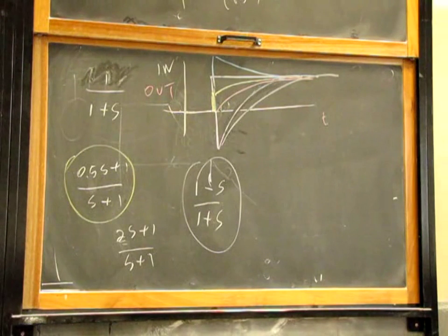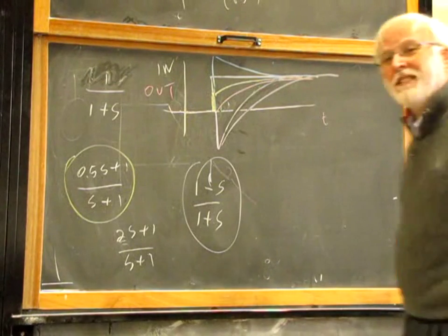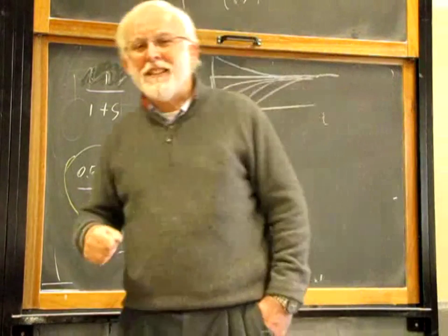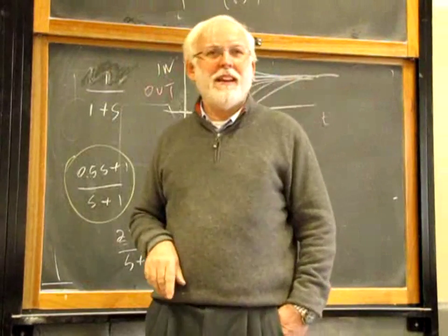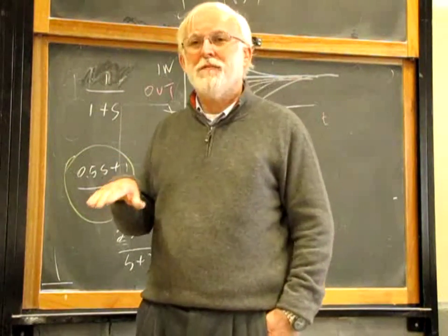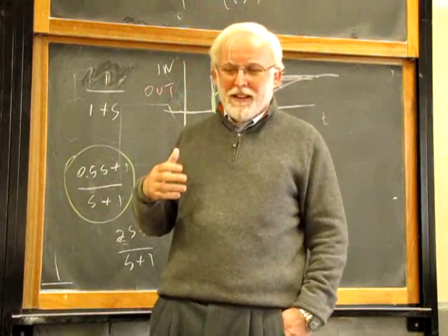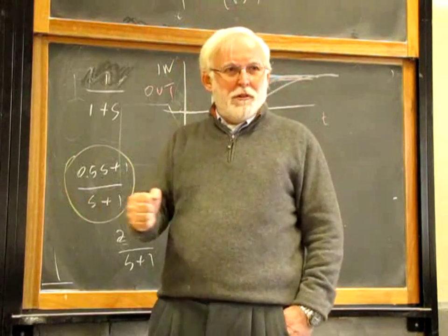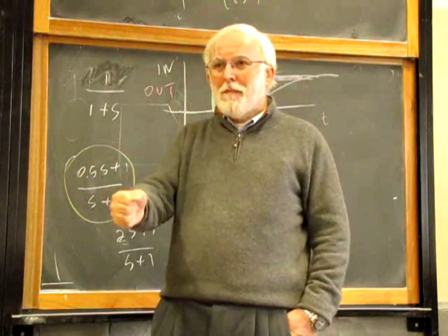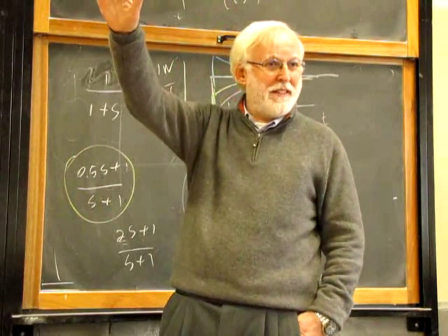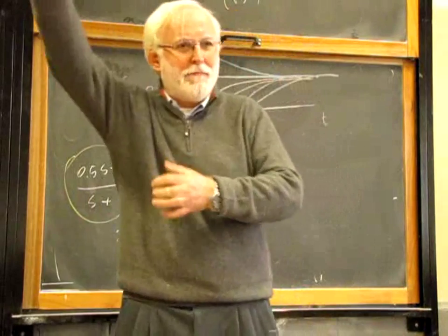Supersonic fighters: when you pull the yoke, it's not a yoke, it's a stick in a fighter. You pull the stick to go up, the fighter goes down and then climbs. And this effect, the right half plane zero, was found by an engineer who solved the system and said, okay, if you want to gain altitude in a supersonic fighter, instead of pulling the stick, just push it abruptly and pull slowly. Pushing it abruptly means you go up due to the right half plane zero, and then you pull and keep going up slowly.